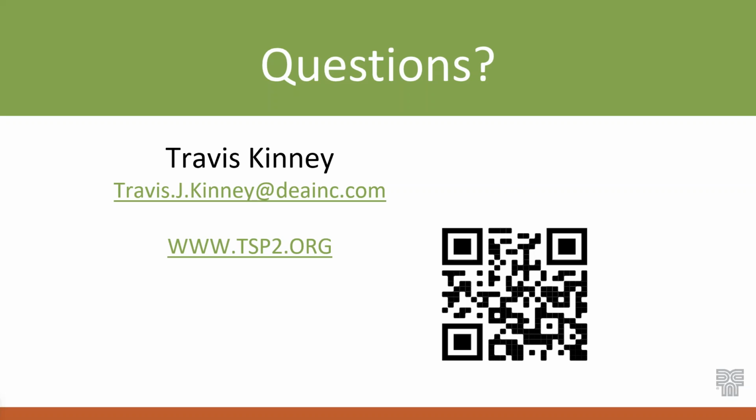Okay, thank you. Matthew, you wrote a good question in here: doesn't a lot of these repair methods give you opportunities to trap water again? Does this not create an opportunity or an issue in the future? I will say that I have repaired people's repairs, and I have repaired the same bridge many times, usually in different spots. It is a very valid comment, especially with that one pile repair I showed where it actually cupped upwards to splice back into the timber. That one I really didn't like, because it does create a pool to collect the water. It's something to think about in what you're doing.